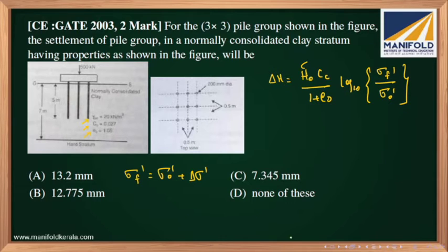So there is an assumption, a condition. If it is an end bearing pile, the load distribution will start from the end. As it is a friction pile, the load distribution will start from L by 3 from the base of the footing. So let it be L by 3. The length of the pile is 5 meter, so it would be 5 divided by 3.